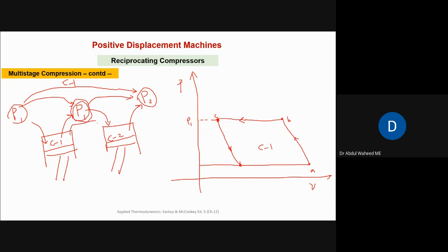Actually, there will be certain pipe which is connecting these 2 compressors, and there is some pressure drop within this connecting pipe. So we are neglecting that effect. So it means we are saying it is leaving at PI and entering at PI in the next compressor. Okay. So now it enters at this pressure into the next compressor at the same pressure PI.